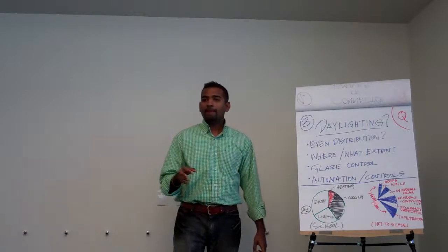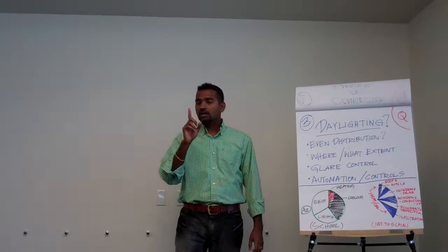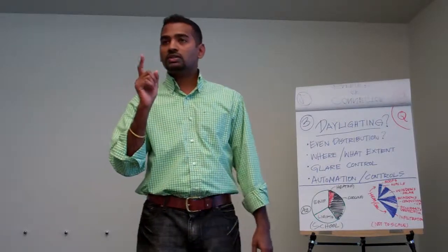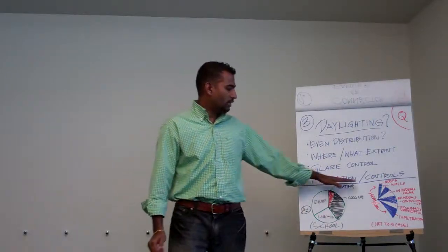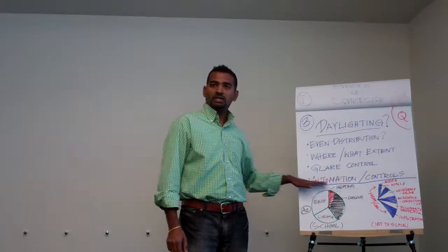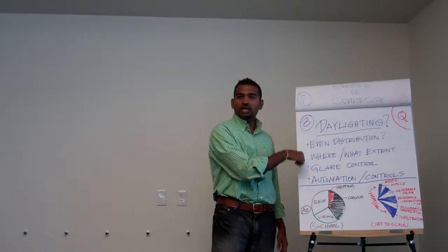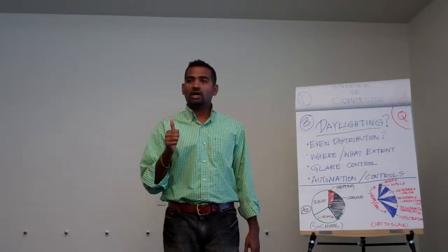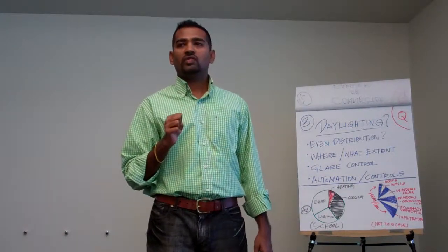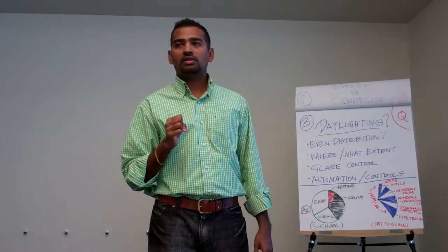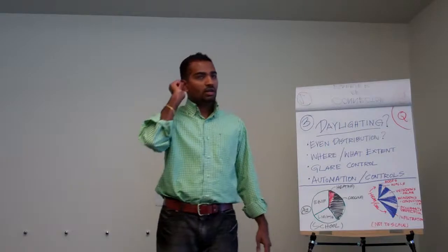But if they don't want automated controls, to what extent does that still have to incorporate how much you don't want to use your lights? That's a very good question, because if they don't want to spend their effort and time on automation and controls, then that changes your daylighting strategy. Because why? You said why? Yeah. Because of how you do your windows at that point.